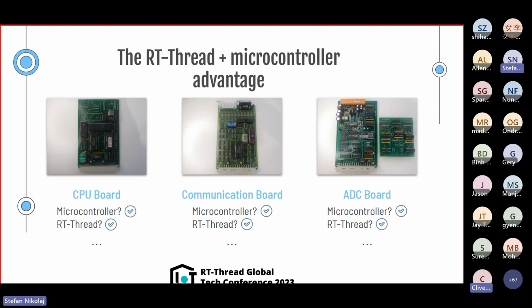So the synthesizer featured a microprocessor with a RAM IC, a ROM IC, bus decode circuitry, and the peripheral chip responsible for handling the incoming UART signals. This arrangement results in high system costs, increased size, and higher programming complexity. Modifying even a single component within the entire system would be very challenging.